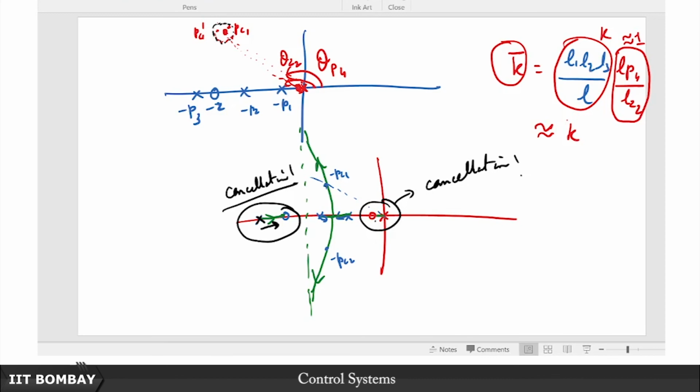What's even worse is this PI compensator that you have introduced now, this PI controller. Now this branch must necessarily be very close to the 0 that you have introduced. Suppose, remember that as k is equal to 0 it's here, as k is equal to infinity it's here. So the entire journey from k equal to 0 to infinity is encapsulated in that small branch, in this small branch here.